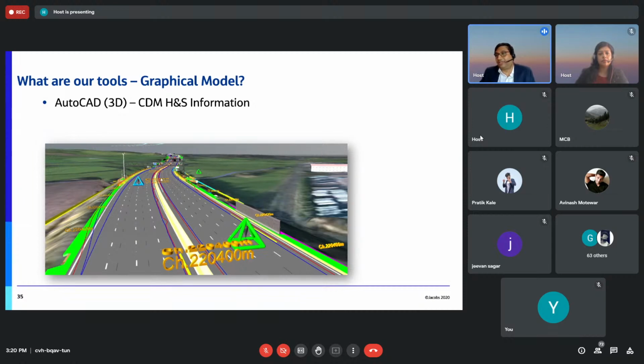At every hazard triangle that you can see there, we have a specific residual hazard which we are communicating to the contractor in this case, because that's a construction hazard. But if that hazard will be faced by the road users as well, we will need to inform it to road users. So that's what we do by those warning signs, if you have seen.